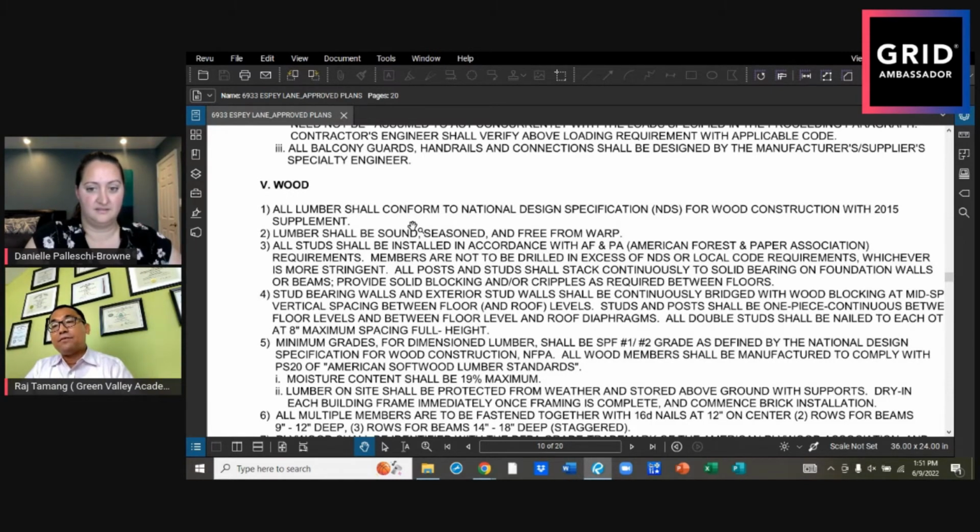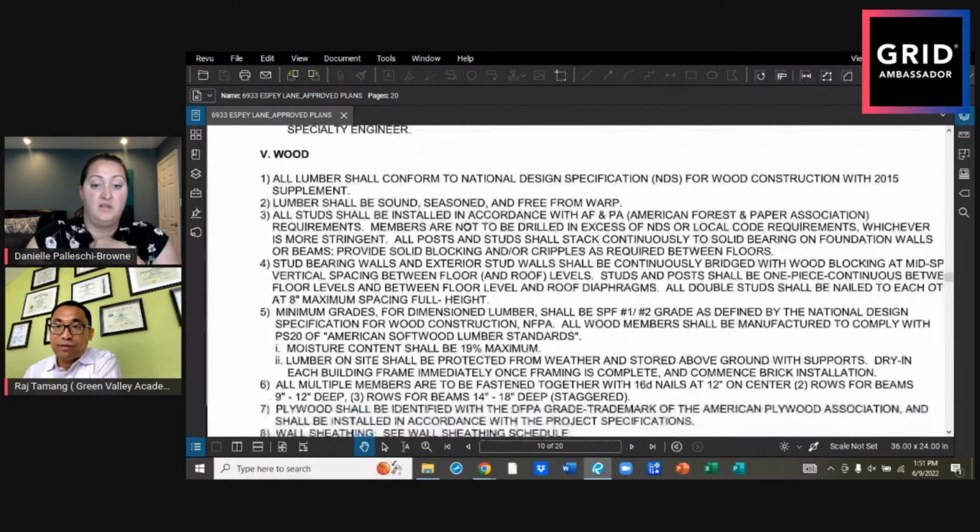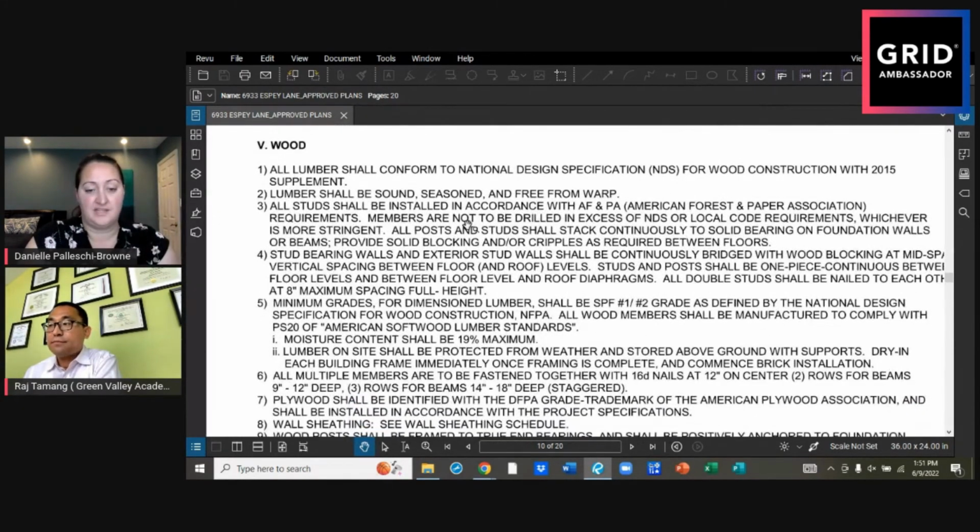Otherwise, how do you know the concrete got its strength? So you do the test, and sometimes you even go to the structure itself. Let's say a slab: you can actually core drill, bring a sample, and do the testing. Kind of like how they drill into trees to test for age. Similarly, you drill into the concrete to test its strength, bring the sample to the lab, and do the testing.